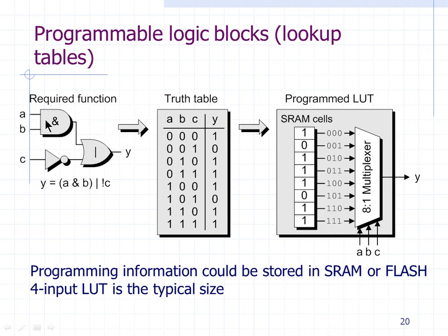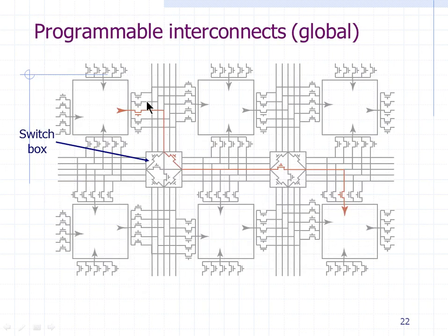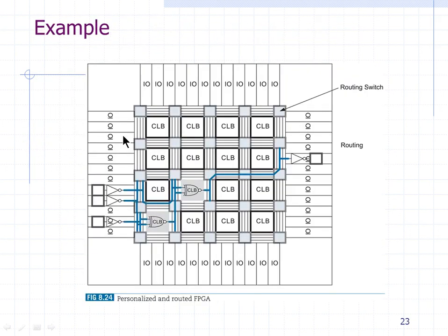The way it works is you write a Verilog for this. Now this is the digital logic circuit given to you. You'll write Verilog for this, and ultimately it will get converted to a CLB and a LUT inside the FPGA. And this is just a programmable interconnect that you will see.